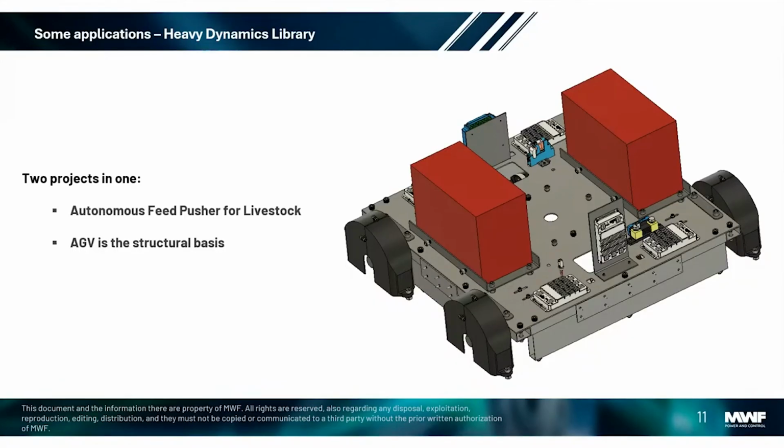center of mass, backlashes, and many other uncertainties that we know we are going to have once the mechanical system is finally realized. So after materialization, we know that the final version of the robot does not look quite similar to the one that was initially predicted during the engineering design phase.